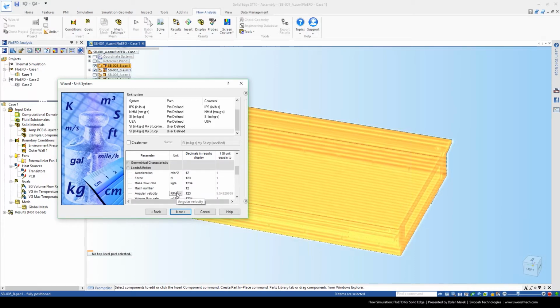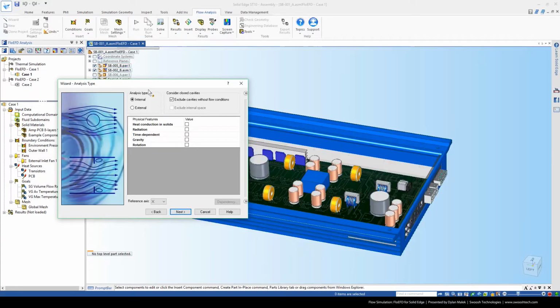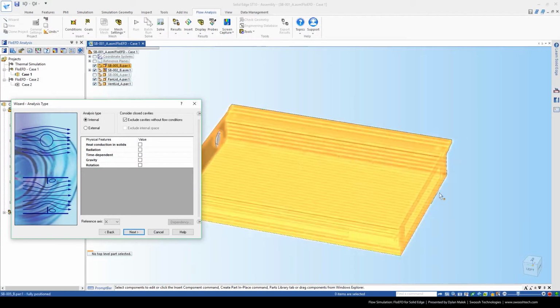As you can see in the list, specifically, I know the motor we're going to be dealing with. I know the RPMs. So this originally was set to be in radians per second, so it didn't have that listing, but if you don't happen to know that, you can always just type in 1000 RPM. It'll convert it. Or you can just change the value anytime you want. So let me put that back to RPM.